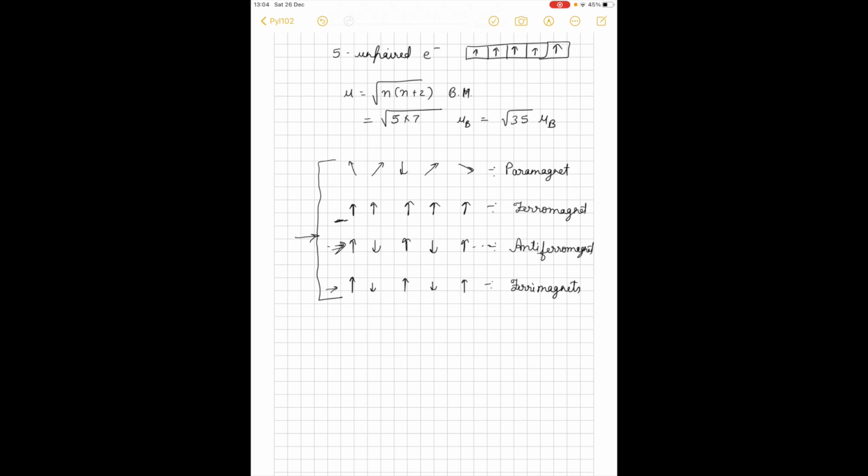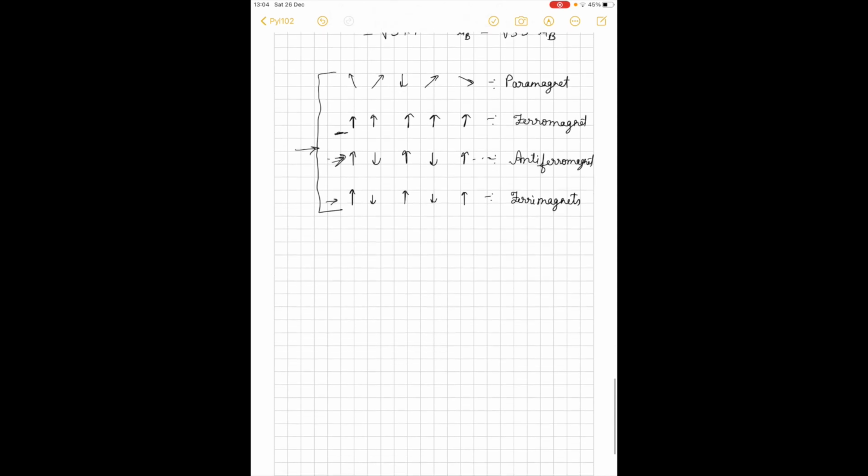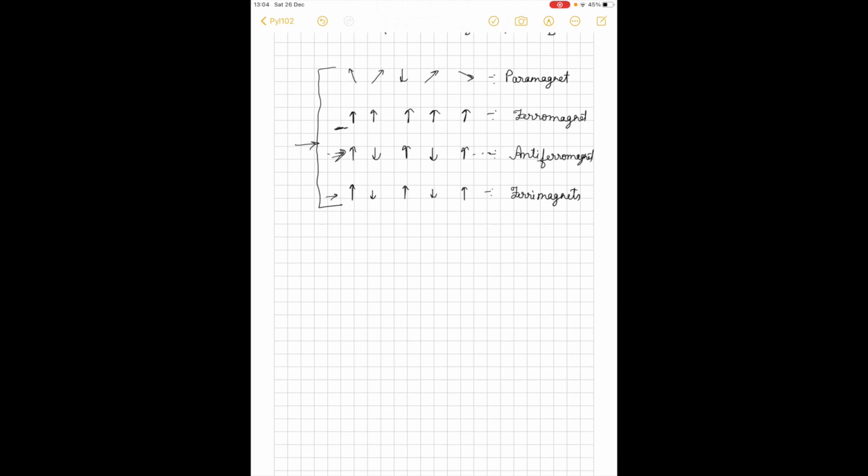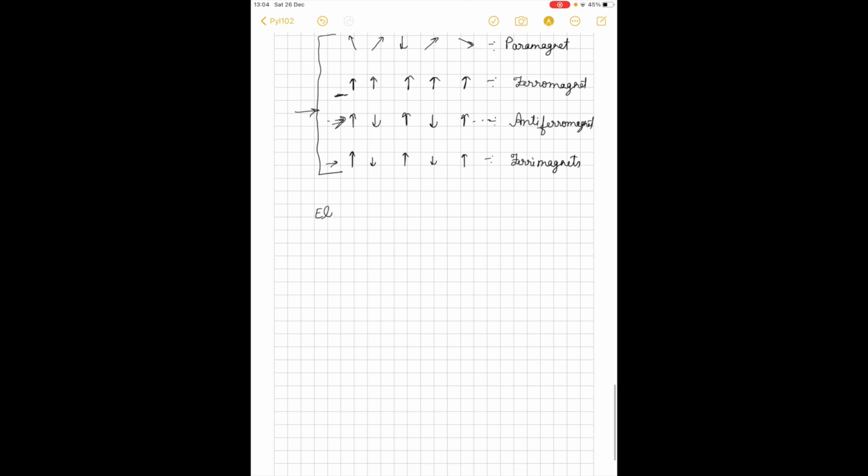Now, from the beginning I'm telling you that dielectric and magnetic materials have pretty much similar quantities and qualities, so I want to correlate those two things. For example, in the electric part, what we saw, and in the magnetic part, what we have seen or will see. In the electric case, we have the electric field as the cause, denoted by E. In magnetic materials, we have the magnetizing field, not magnetization, and this is denoted by H. So these two are the cause in the respective materials.